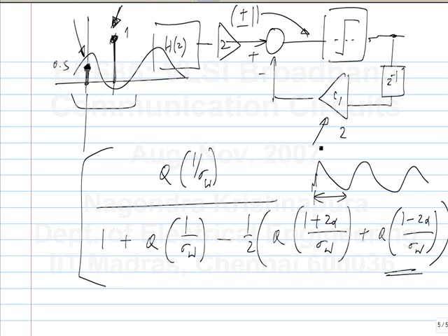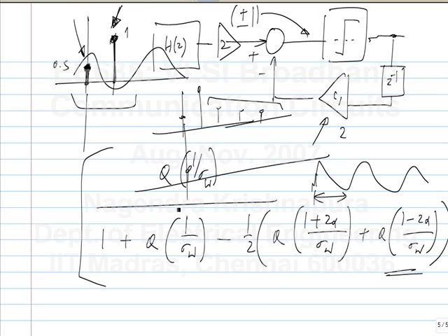So for the sake of the assignments, I just took some channel, and if it had the largest one, one previous to the largest one and 3 following the largest one, I said the equalizer also has the same thing, but it turns out that's not the optimal either. If you do the simulation with an equalizer which has the largest one, 2 before it and 2 after it, that gives a better performance. But I don't know how to analytically arrive at this result. Okay. So maybe that should have been part of the assignment also.